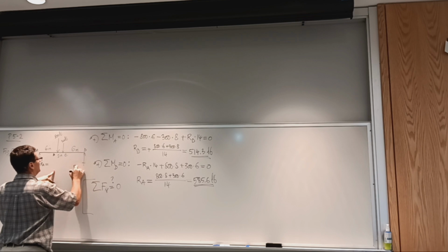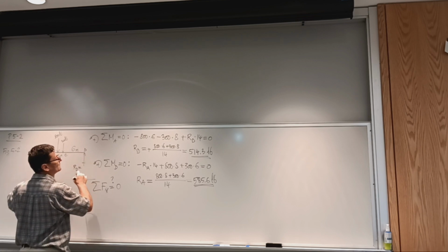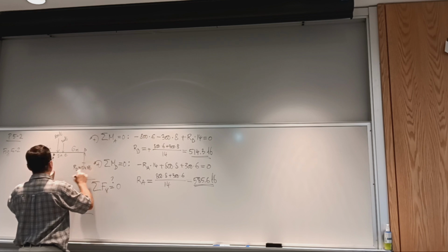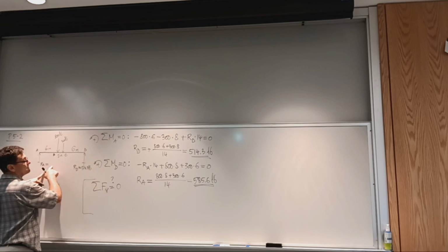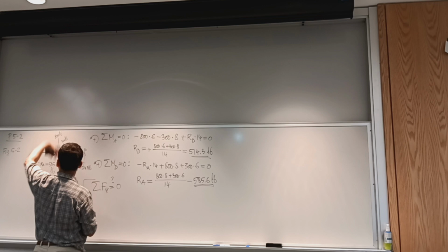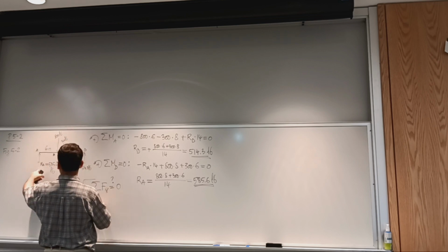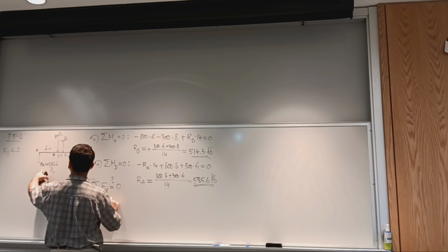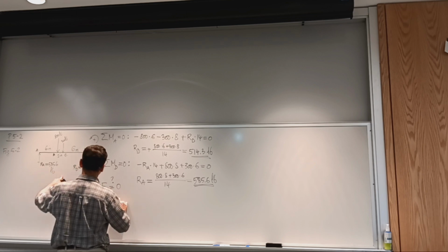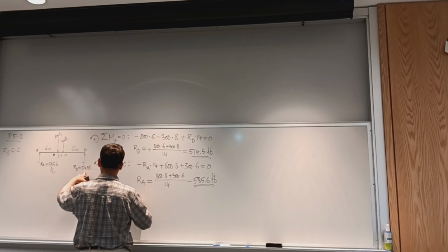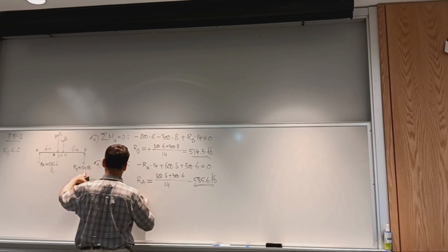So RD equals, we got that first, 514.3 pounds. And then this other one is 585.6 pounds. All right, so positive, negative, negative, positive: positive 585.6, negative 800, negative 300, positive, the last, the reaction at D, 514.3.